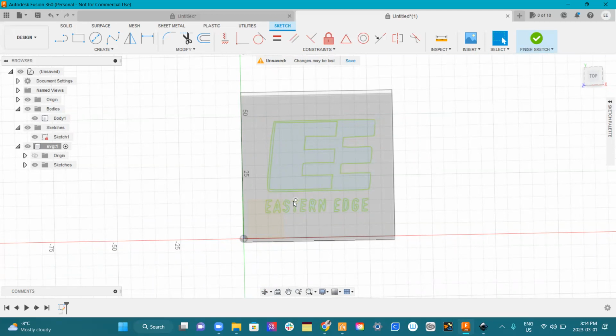So in order to do that, I had a drawing that was lines, and then I used engrave. And so the engraver will follow the lines. Like in this one here, I'll hover there, the green part, to see. So you can get it to trace out that line, but like the logo, this part here is black. If you're doing a print and you want that whole region to be flat, engraving is not the ticket. So you've got to decide here, what way do you want it to draw this thing? Is it a set of lines, or is it a set of areas?